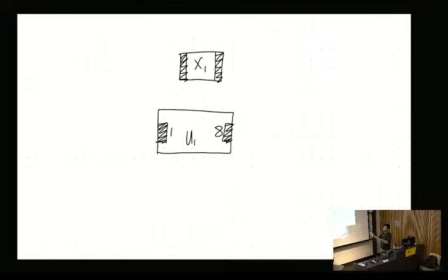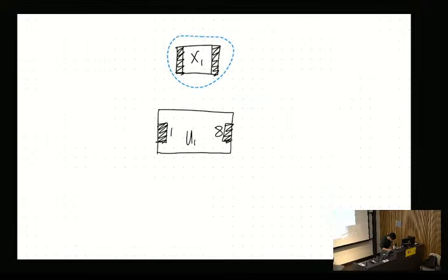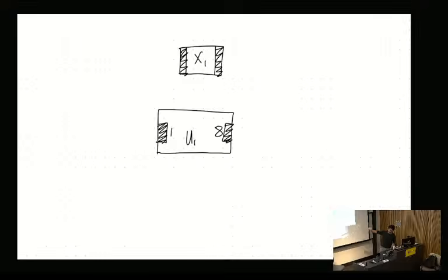Now, what's really important with a crystal and any differential signal is that you keep the traces on both sides identical. They must be identical. In this crystal, because it's a really precise oscillator, the parasitics on both return paths need to be almost identical. If you're carrying any differential signals on a PCB, the trace lengths must be identical, and the amount of parasitics they encounter must be identical, because it's effectively a differential signal. That's why I've drawn it in the middle like this, equidistant between both of those pins.